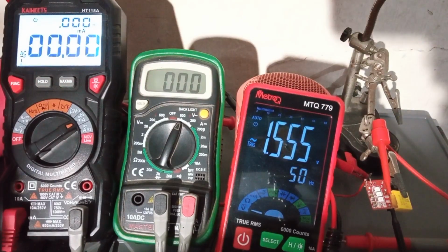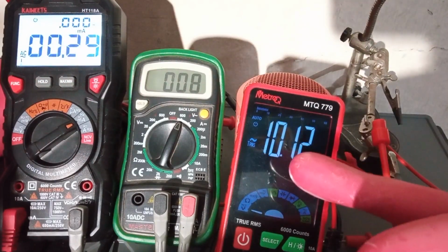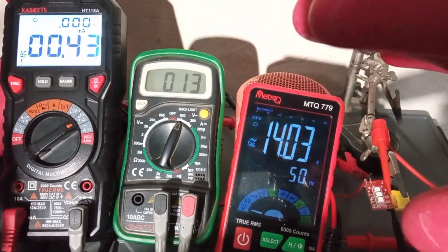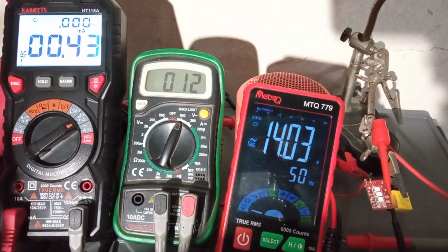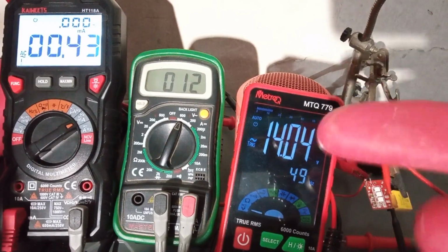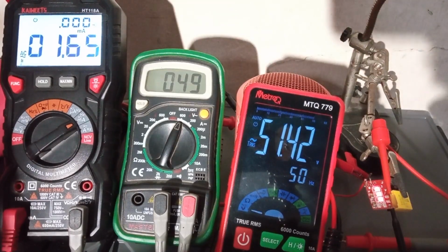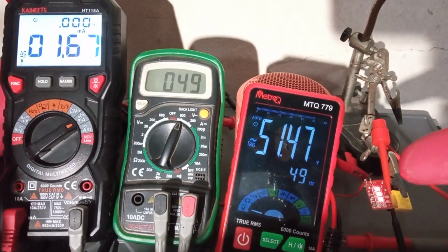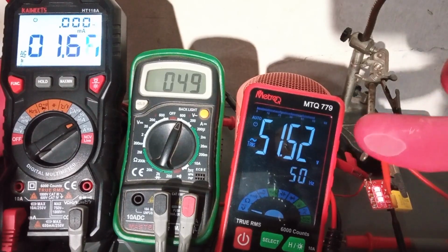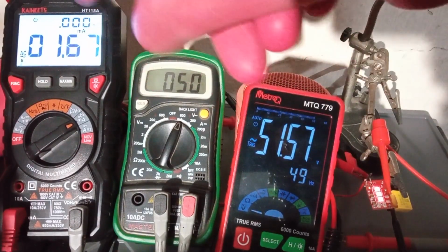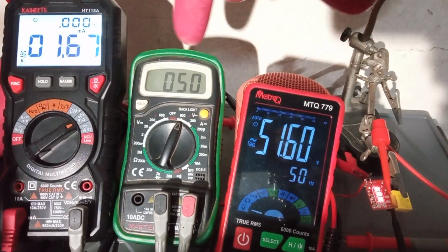So if I turn my auto transformer on, currently we are around 13 volts, and the light is glowing very faintly. So it starts from around 14 volts AC. This will of course not work at DC, because the capacitor will just block that. At around 50 volts, the light is nicely visible, but it is quite faint. And at 50 volts, we are drawing around 1.67 milliamp of current.